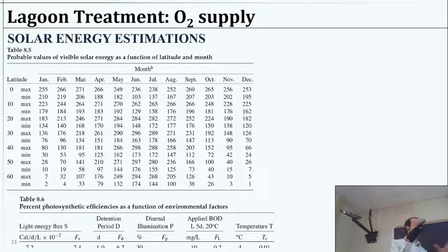So all of these factors would go into telling us how to design a pond that could accommodate this much biological oxygen demand, this much wastewater, given how quickly these processes will happen. So lots of moving pieces there, but you can imagine this would all go into some design criteria, or some design equations to meet a particular criteria, right?